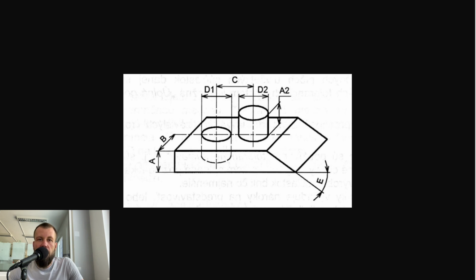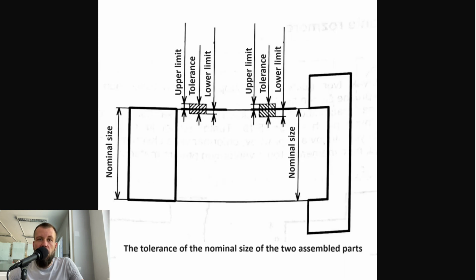Tolerance is therefore a system of accuracy and deviation from the nominal dimension and is given by the allowable inaccuracy. To ensure the functionality of the fit, the actual dimension of the product needs to be within the tolerance.